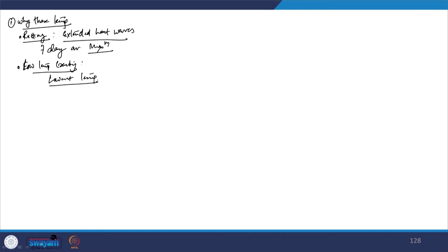So, which means that even a single low temperature is sufficient to induce cracking, or thermal cracking, in the mixture. Of course, there are also chances that if the low temperature is not low enough to exceed the tensile strength of the HMA, it will not crack.